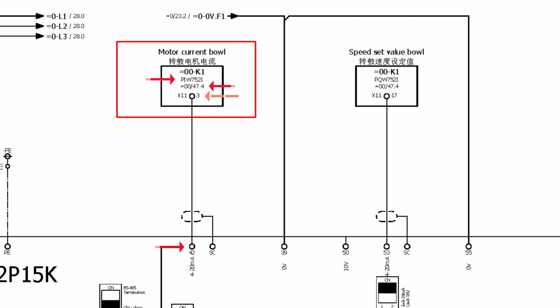You can see it giving us the direction that from VFD terminal number 42, it's going to PLC analog input channel PIW7521, which typically refers to a specific channel or tag associated with an analog input card in a PLC, which will help to identify the channel.